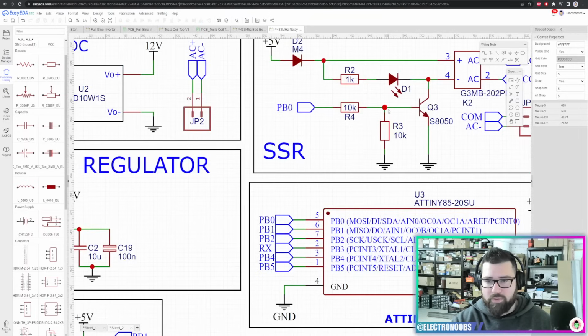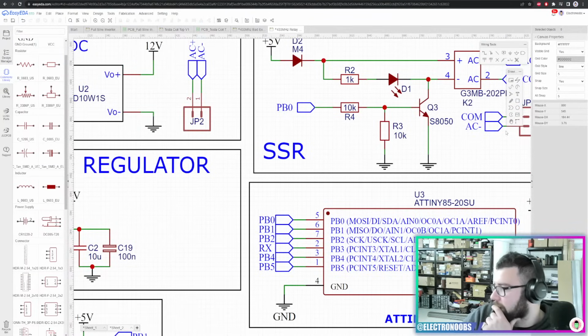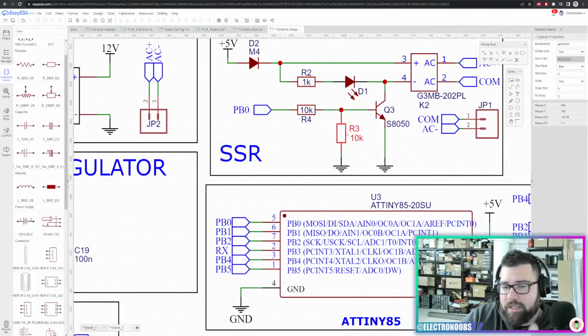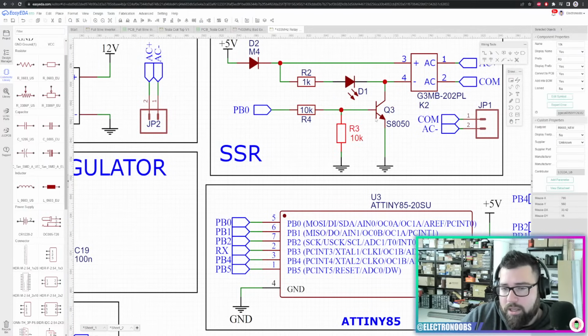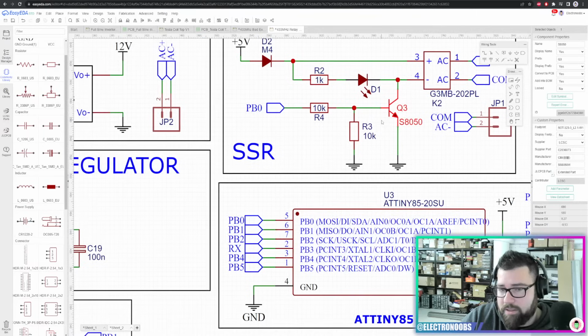I mean, I do have a voltage divider, but that's not a problem. And not sure what you suggest. How you would do it without this resistor here, just a plain connection directly to the base of the transistor. I mean, you need a resistor as a pull down, so when this is not connected, this will be turned off. And you also need a resistor to limit the current, because otherwise this is a BJT and the base of the BJT is opened by the currents, and you don't want to place a huge amount of current here when you want to turn it on.